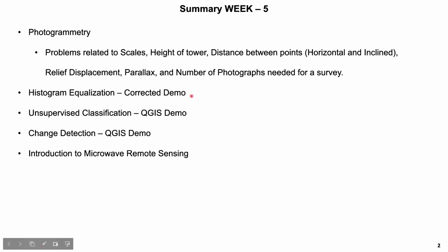I have discussed about the corrected demo. So there was an issue with the data type involved, so I was saving it as integer 16 data type, but since we are converting from 16-bit to 8-bit, the saving type should be 8-bit type. So that was the error. So I have uploaded the correct procedure for that. Then I also did a very quick unsupervised classification demo in QGIS, and followed by change detection, how to do it in QGIS. Then a brief about remote sensing.